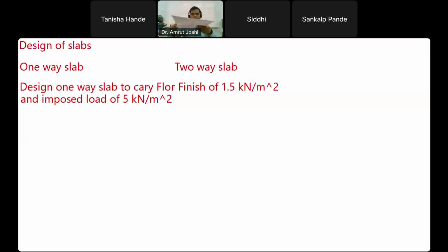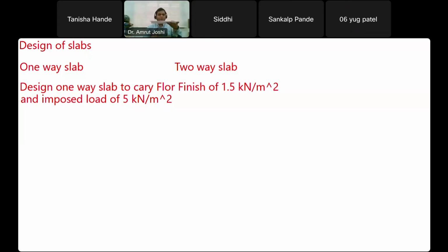Now imagine you have a slab which is square in shape. Now, if it is supported on all the four sides, not on two opposite sides, if I put anything in this, it is going to bend in this direction as well as like this. So you are going to get a saucer-like deformation. It bends in this direction as well as in this direction. Are you with me? Yes, sir. So such type of slab is called two-way slab, which bends in two mutually orthogonal directions.